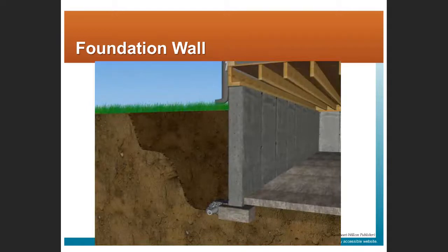Again, a picture, right, in plan and kind of a representational drawing of a foundation wall. Right, so you see the foundation wall, the footing, in this case a basement slab. And in this case, there's also a drain tile, surrounded by gravel at the base of the footing.